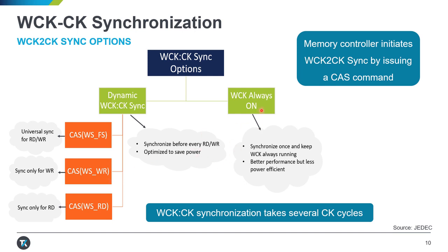In WCK always on mode, once the synchronization is done, the SoC memory controller will keep WCK toggling at its full rate, regardless of the DQ operation. Now this mode offers better performance since we don't need to synchronize WCK with CK before every read and write operation.